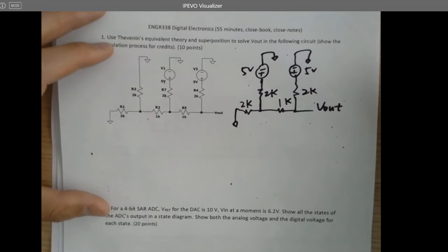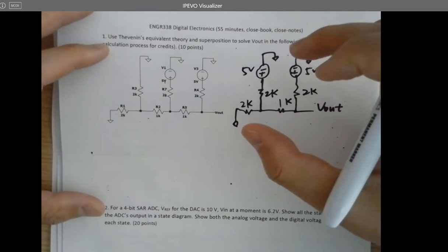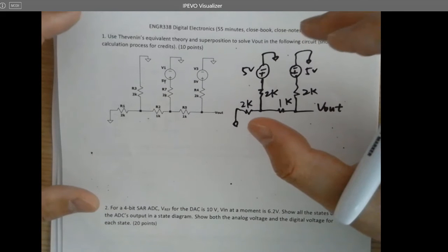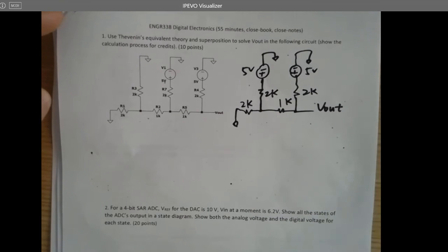Have you realized that superposition is super important recently, but not in Circuits 1? Not just over here, but also in the op-amp. Remember when we are trying to add a DC offset from the other terminal, it's also a superposition. You just ignore the other one, you just add a DC voltage across the resistor. It's going to lift the signal up. No matter what the AC signal is being applied to the input, it's going to lift it to that DC level. Right? It's also superposition. How to understand it? I mean, you just directly add a DC voltage across the resistor. Or trying to use a mesh or anything else is complicated. But if you just think about the entire thing using superposition, it becomes super simple. It's just adding a DC voltage to it.